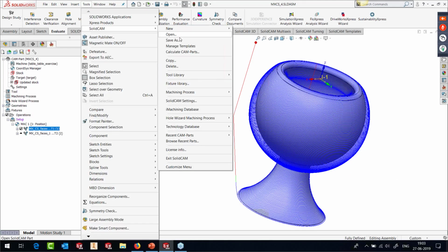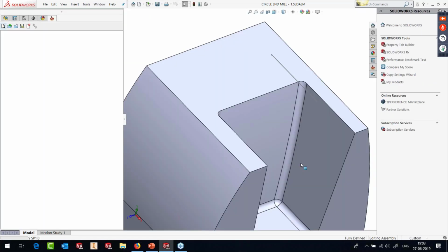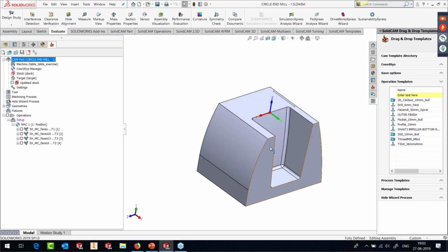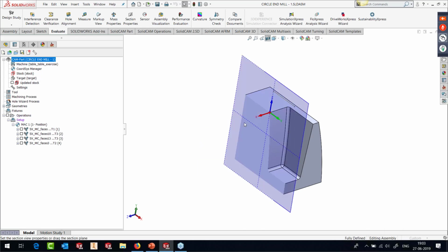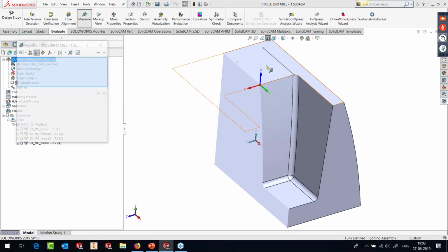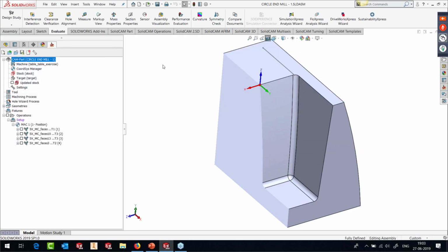How we handle it apart. So I've got a pretty deep part here, and I know that I cannot use lead angle because if I look at the distance, it's about 125 mm of machine. But if I use a ball, I need to tilt it and I'm limited by the radius of the tool, and I cannot give bigger depth of cuts.